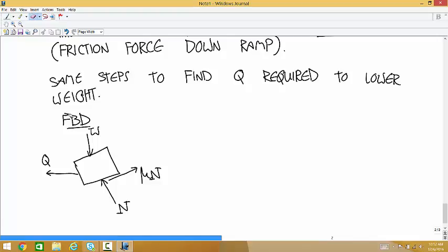What's the difference when you're pulling or pushing through the screw? Are you screwing the screw tighter or screwing it looser? If you're making the weight rise, or pushing against whatever force is being applied, a bigger force is going to be required to do that. And that first calculation we did was how to do the math. If the weight is actually helping you do your job, like it is in this case, if you're trying to get the screw to slide to lower, you're going to get a smaller force Q required.